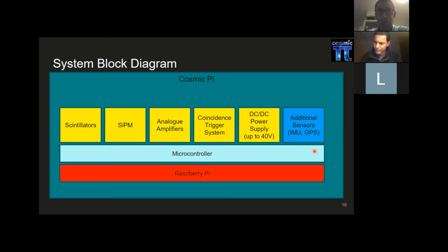And then finally, we have a GPS. This gives us the X, Y, and Z locations, but most importantly, also the timestamp. We use the pulse per second, which is a common output from most GPS modules, to synchronize Cosmic Pis in a network. All of this plugs into your microcontroller, and this handles the hard real-time part of it: detecting events, timestamping, and once a second in our architecture, it gives a readout to a Raspberry Pi, which then processes that information and makes it available.